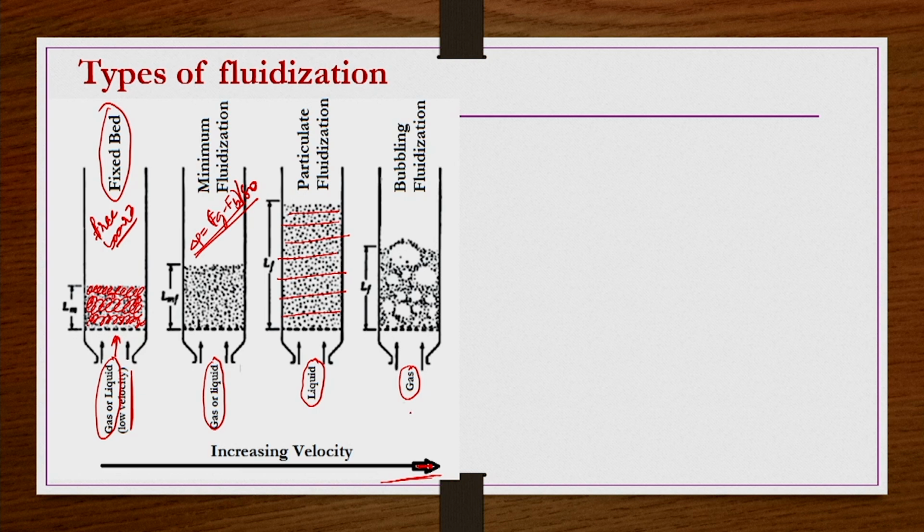However, if your fluidizing medium is a gas, then as the velocity increases, there will be a situation where bubbles, or voids, may be forming, which are almost free of particles. There may be 1 or 2 particles, but in general these voids are free of particles, and you can see those bubbles are moving up rather fast compared to the bed.